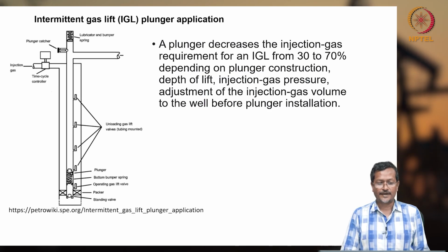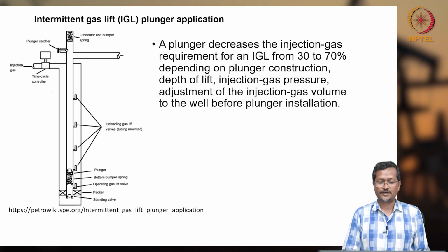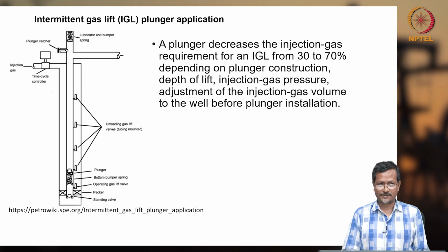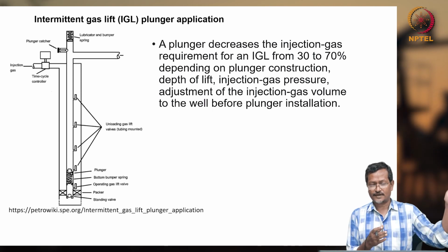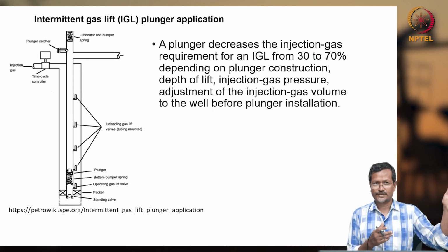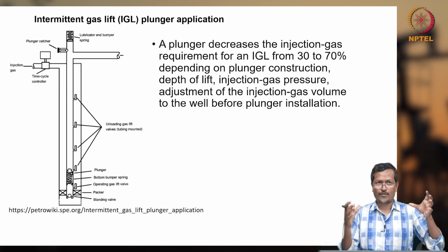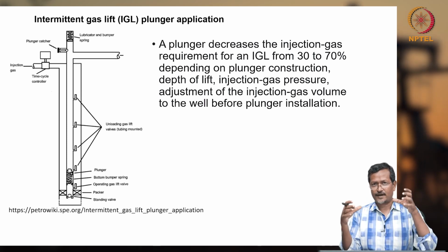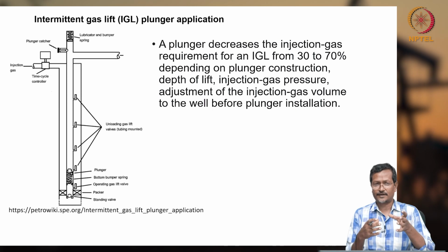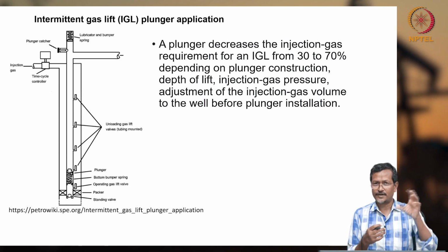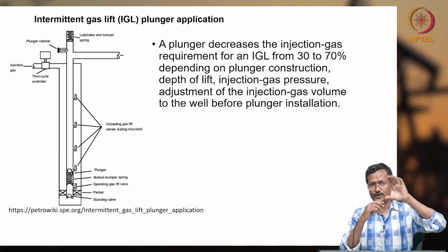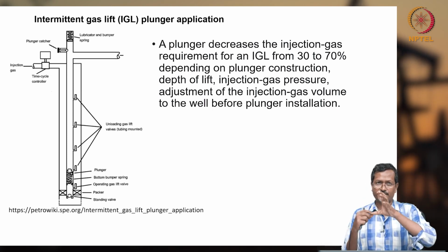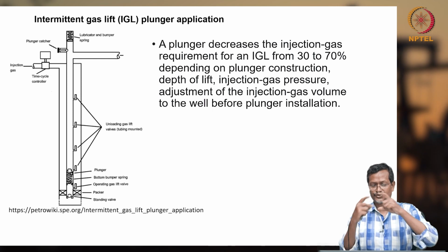Intermittent gas lift in IGL plunger application. In plunger lift application, I said that normally there will be no gas injection, while intermittent gas lift application has gas injection only. So, there is no plunger. Now, people try to combine intermittent gas lift and plunger lift application. Both are intermittent gas lift applications, but in purely intermittent application there is no plunger, there is no interface between liquid and gas. In plunger lift application you have one interface, the plunger.